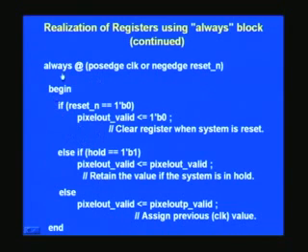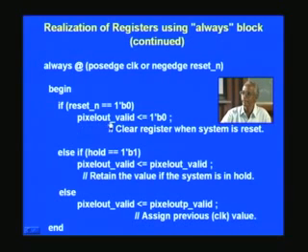And here, once again, what we have seen is when reset is asserted, this pixel out is the actual signal that we want. Earlier it was pixel out P, indicating the prior signal for this. This is the actual signal that we want, a delayed signal. But the actual signal was already pre-computed in the earlier cycle. So now, once again, we reset, because when a reset is encountered, we have to reset, and that's what we have put here. And if hold is there, just hold on to the same value as such. And if not, we don't.